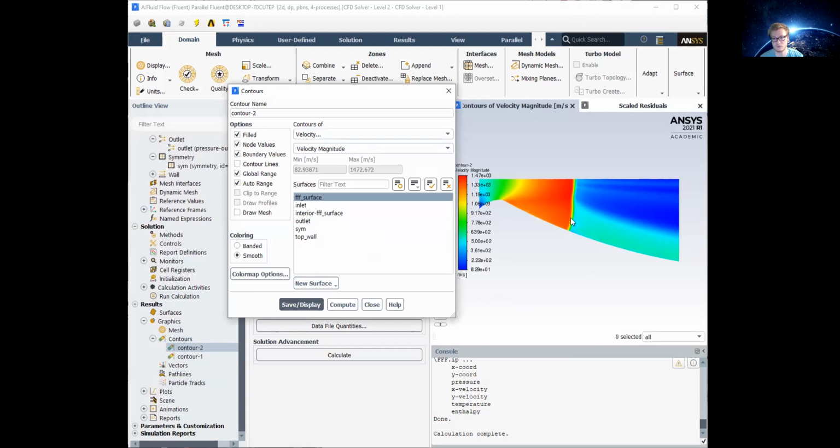If it was a normal shock wave at the exit, you're going to see it continuously increase. But since the shock wave's right here, it's going to drop off in velocity, and it's going to become a diffuser. And as you know, with diffusers, you're going to slow your velocity instead of increasing it, like in the case of high-speed aerodynamics. So it's just going to keep dropping from here, except for around the wall. The wall is going to keep around the same velocity because it's kind of being funneled.